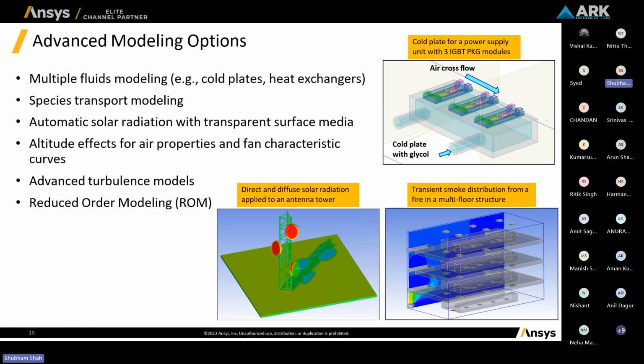And what this simulation is done for and how it's exactly performed is, let's say you are in a multi-level car parking, and if a fire takes place in any of the stories, how your smoke and fire will propagate, how your smoke will fill up the ceiling, and up to which level your smoke will travel until the fire is stopped. In this kind of simulation, you can see the area coverage of smoke, how dense the smoke will go up, and after what time it will come to half of the